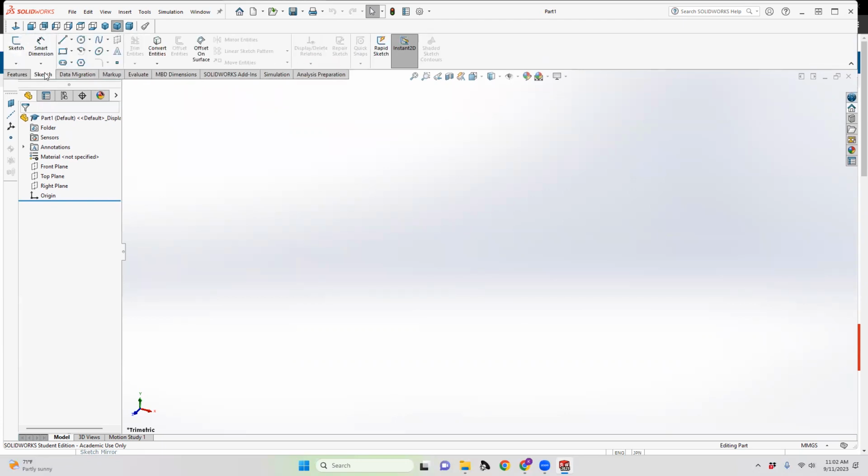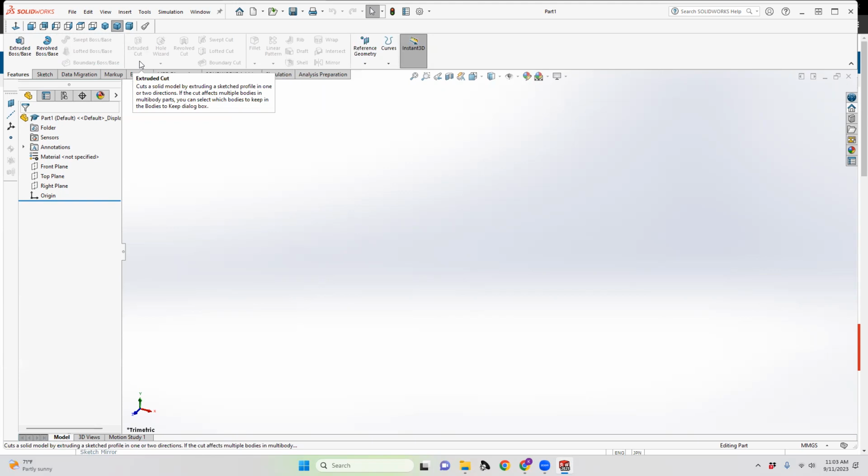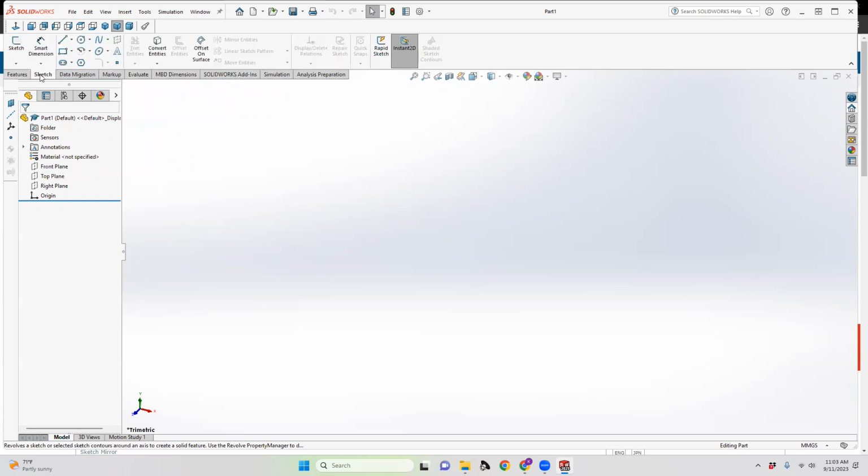You want to make sure that the sketch is the one you go to first. So sketch is what you're doing on 2D planes. Features is how you tie all of those things together with 3D processes. That's the way to think about this. So you perform a feature on a sketch, and the sketch is kind of where we're going to start for today.